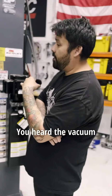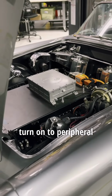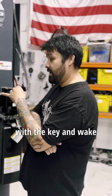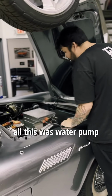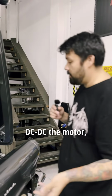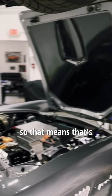Right now you heard the vacuum pump turn on. I swapped that from an ignition turn on to peripheral power on the output. The fact that it actually turned on right now with the key and wake means that the actual output and the pinout is correct. The reason we're doing all of this was water pump turn on for the auxiliary components like the DC-DC, the motor, all that stuff, meaning the drive system. But now I've got fluid moving, so that means that's working too.